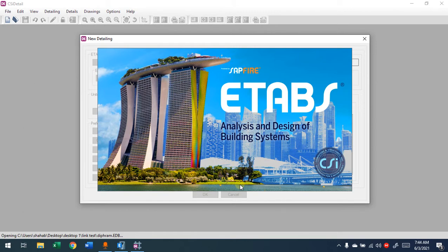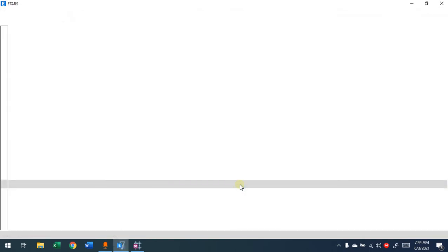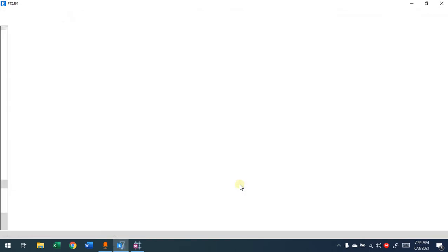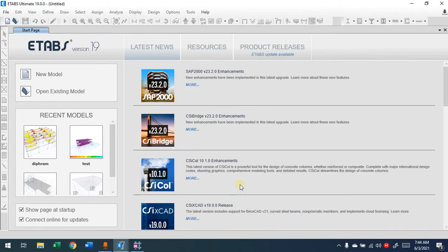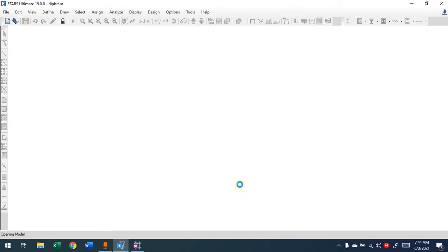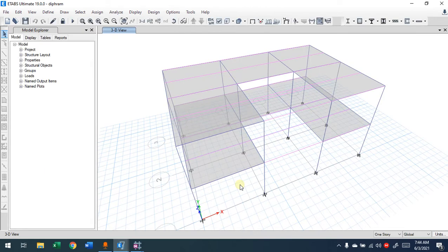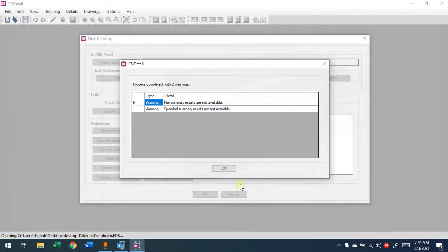Go through all the information. So it will take the grid, the sections. Mainly we'll go for the design part, which looks for the reinforcement. Since it's concrete here, it will bring the reinforcement, section detailing, everything back. It will not generate it directly. It will ask you a lot of detailing, a lot of preferences that you have to select. So normally we'll open ETABS again to gather the information required, and we'll bring it back.